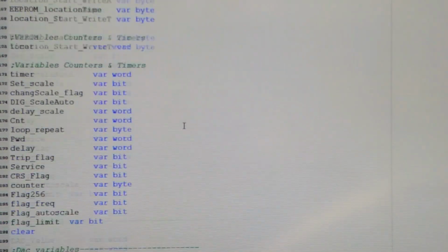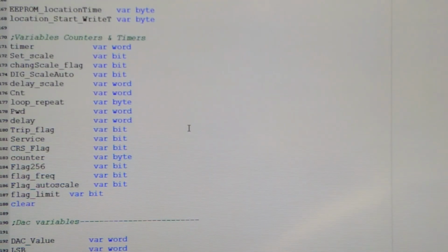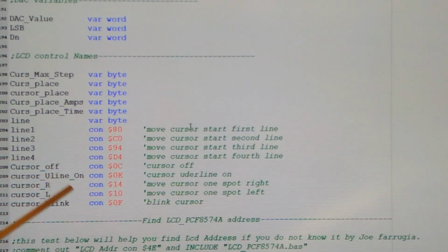The only problem with that is that it takes a couple of steps longer, and also, if you use a pause command, for example, let's say you do pause 1000, which means you're pausing your code for 1000 milliseconds, which is 1 second, it means your interrupt will be delayed for 1 second.